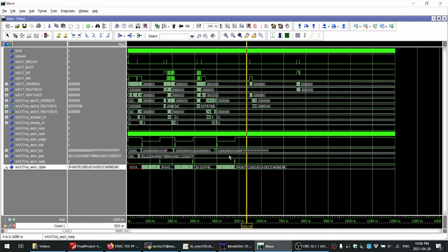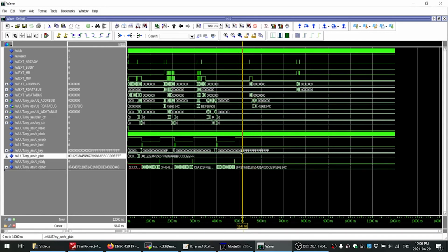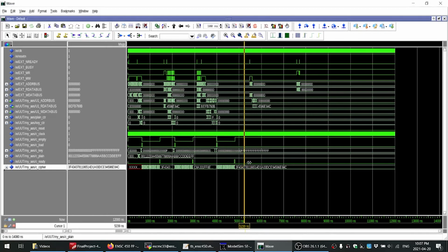We designed the test cases so that even though the data is being inputted to the AES core from different sources, it's the same data, and as we can see, given the same data, it produces the same output. So this verifies that the AES core has been properly integrated into the SoC. And in this test bench, our AES integration passes this test bench for both the front end and the back end.